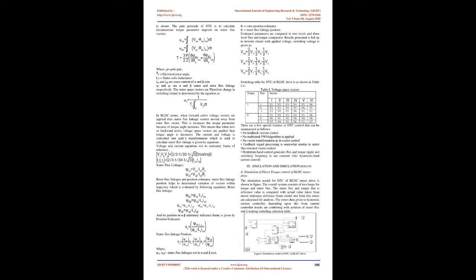By selection of voltage vectors, the flux trajectory, i.e. circle or hexagon, is produced. In this technique, the states of the power switches are determined directly by the determined and reference torque and flux signals. This is accomplished by utilizing a switching table, the inputs of which are the torque error, stator flux error, and stator flux position, which is divided into 6 sectors of 60 degrees. The switching table output is applied to the inverter, which depends on the error signals.